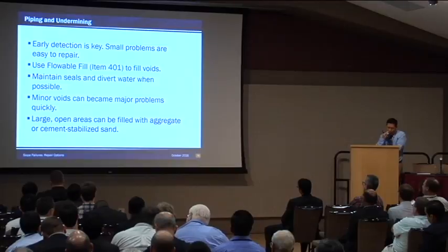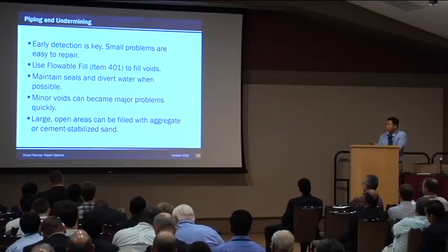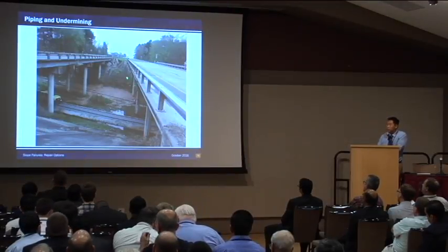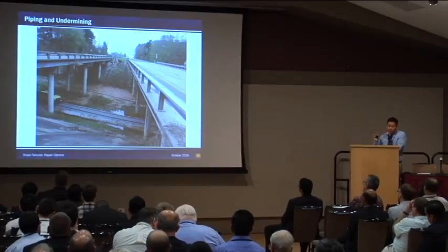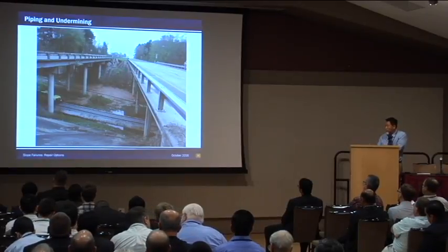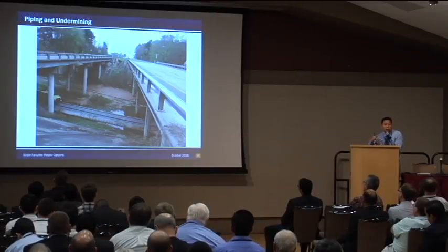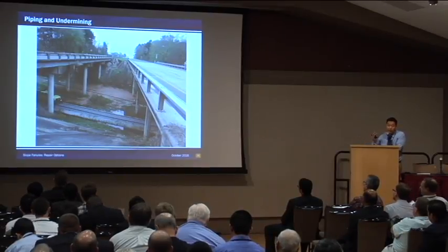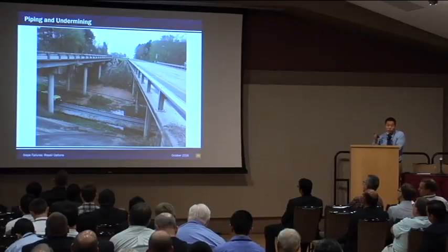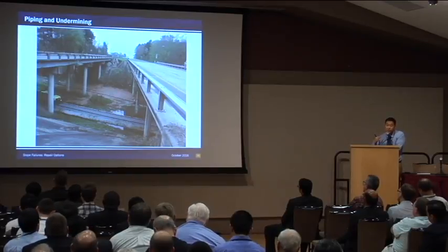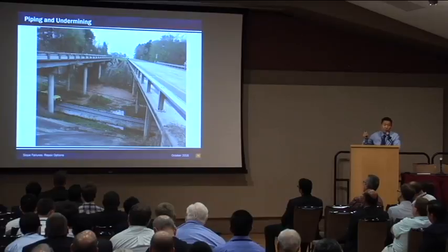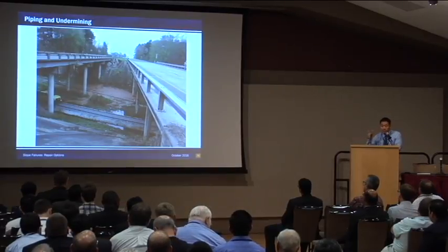One of the problems of undermining or erosion, especially at the bridge abutment side, is if you lose the soil, the header bank. There will be the abutment structure, with either a drilled shaft or piling, so it depends on the geometry or the embedment of your foundation. The foundation may lose its lateral stability, so somebody needs to check the lateral stability of your abutment foundation.